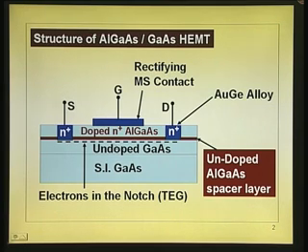And to ensure that this top layer, the heavily doped layer, does not participate in the conduction in any portion of the device operation, you ensure that the entire layer is depleted. Okay. So, what we have computed also is, we have seen that the voltage required to deplete this entire top layer will be VBI minus Vp0, which actually is the equivalent of the threshold voltage of this top layer, just when it is depleted.